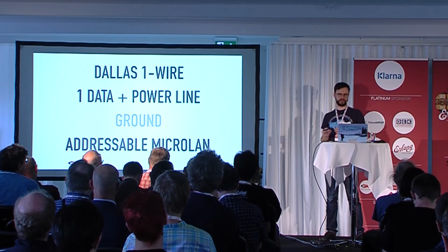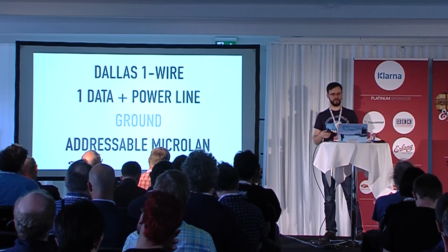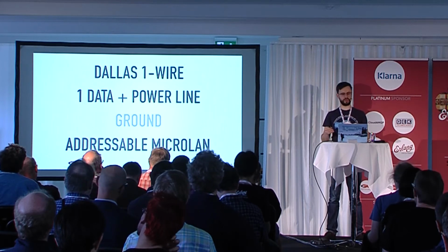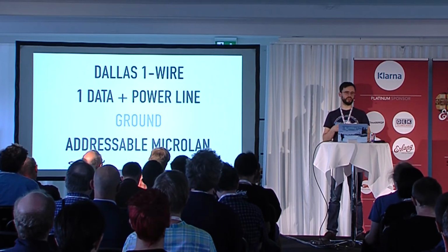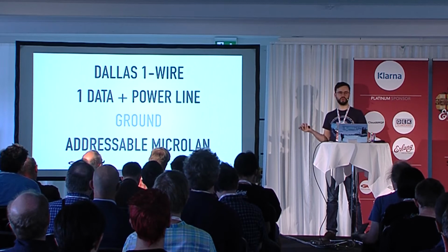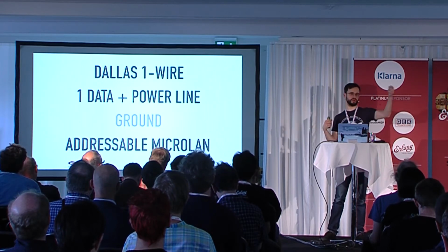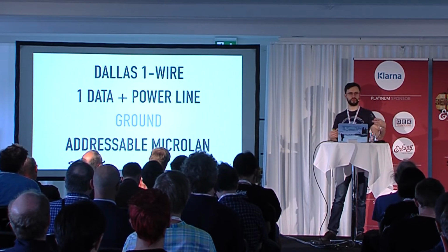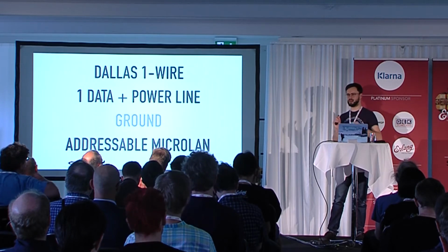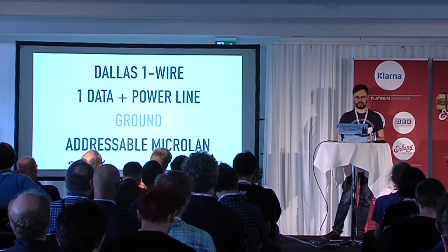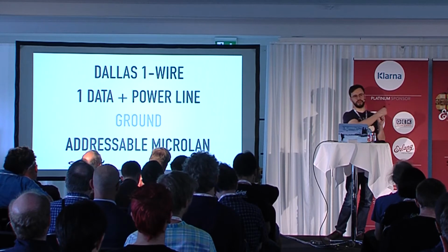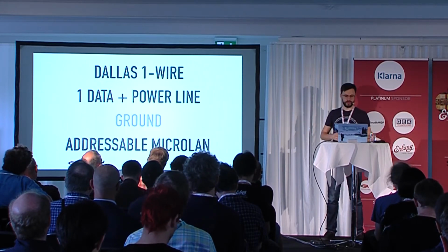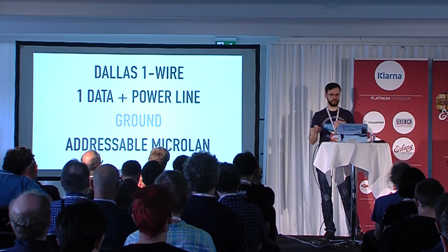And it's similar to I2C, so you have addressable clients and so on, but it supports much longer distances. So we're talking room or house scale, where you can draw wires. If you have this one sitting in a corner somewhere, you can pull temperature sensors around your house and then get all the data back. And you only need this tiny 1 wire system. So also in this one, it's kind of a MICROLAN.